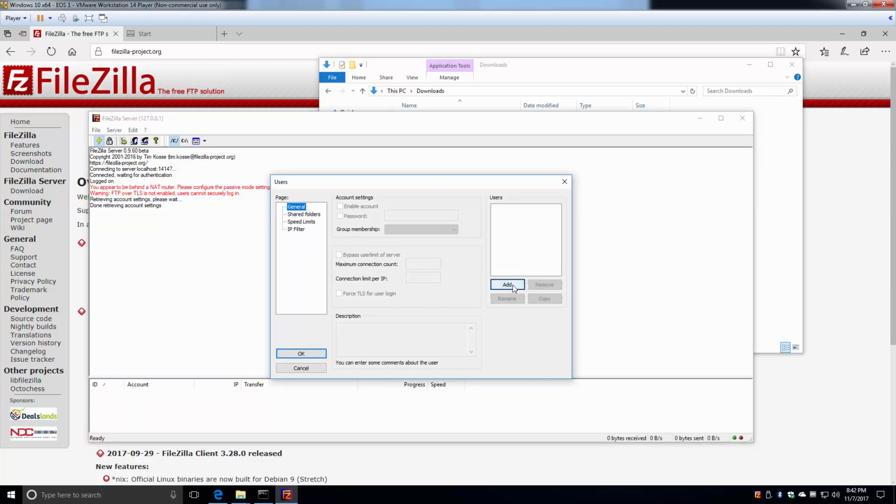There are a lot of different ways we can attack this. I typically keep one specific user, but if you have different directories or different functionalities, it may be a good idea to have multiple users. So for example, we can create a user called nanodac. It's very generic, for archiving data. But because the nanodac also has the ability to connect to an FTP server to pull recipes for the setpoint programmer, you may want to create another one called nanodac recipe, or whatever you want to call it.